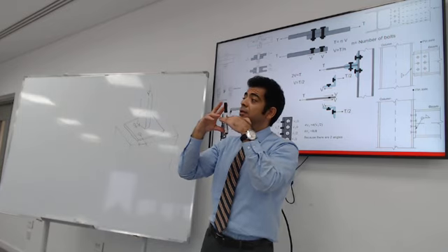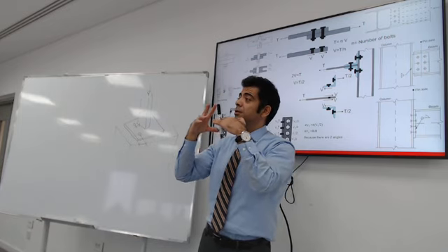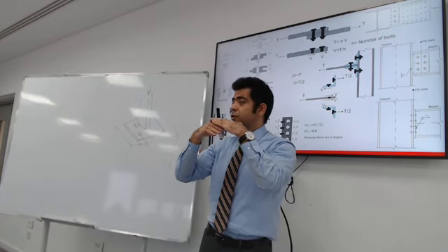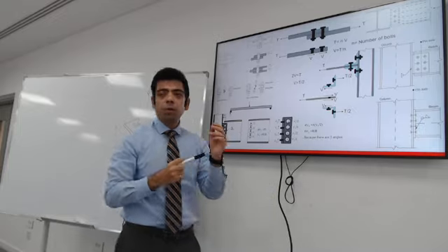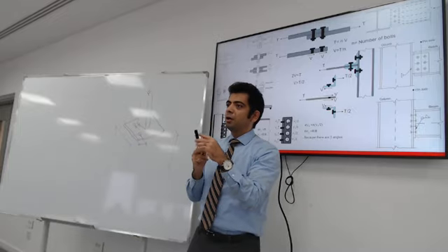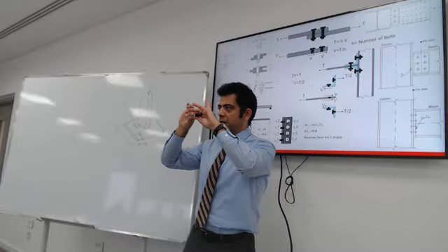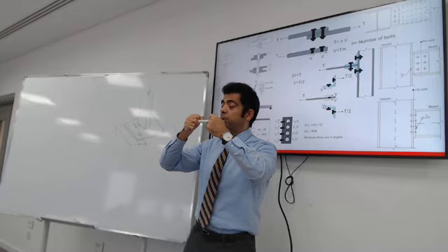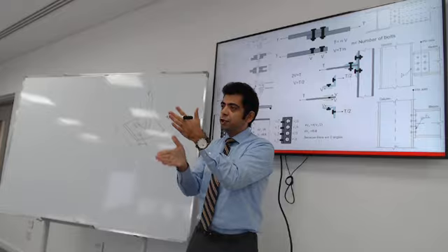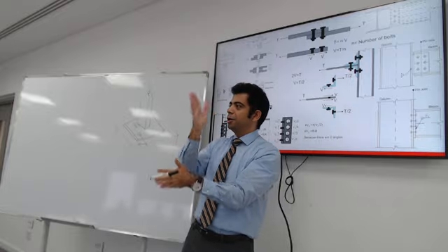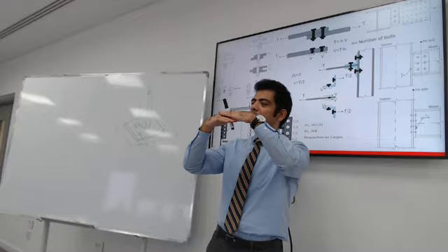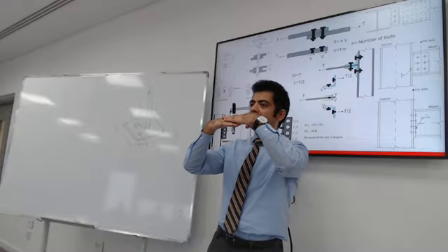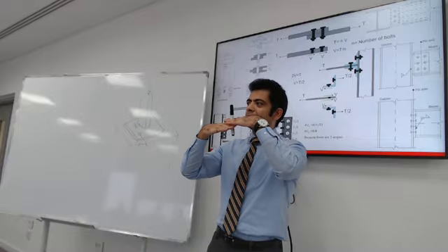Is it causing tension on the bolt? Is it causing other stresses on the bolt? So the bolt can take either tension force, you can apply tension on the bolt, or you can have shear on the bolt. You can shear the bolt. So when you have two plates like that holding the steel connection, these horizontal forces, what are they?